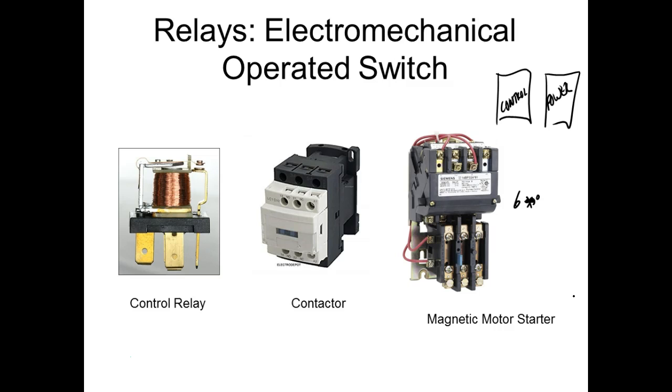So this is the control relay. Like I said, this is where we would hook up the coil. Then when we energize this, it would cause the solenoid to move, right? And it would cause this to move and you connect it to the contact. So this control relay has eight such contacts. You can look, one set is missing.